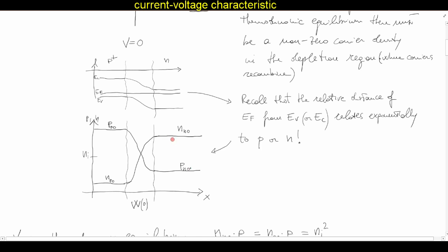So I will start on the other side. So here I have a lot of electrons. So how many? A little bit less than this density, because we said it's P plus N. So the density of electrons is less than this. I will do it just a bit lower. In my mind, I'm assuming this is a logarithmic scale. And on this side, this will be the level of electrons. Here there are many holes, so very, very, very little electrons. Because this is a little smaller than that, this is a bit higher than this one. I remember the mass action law.